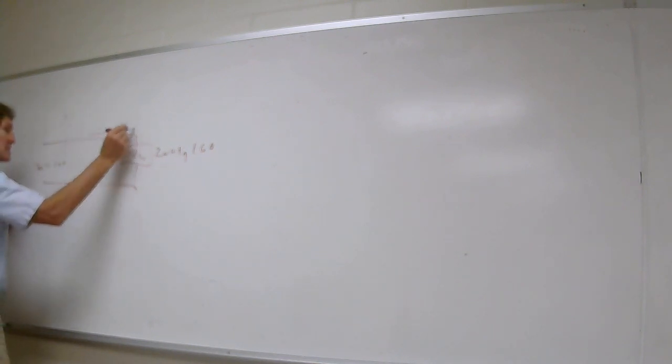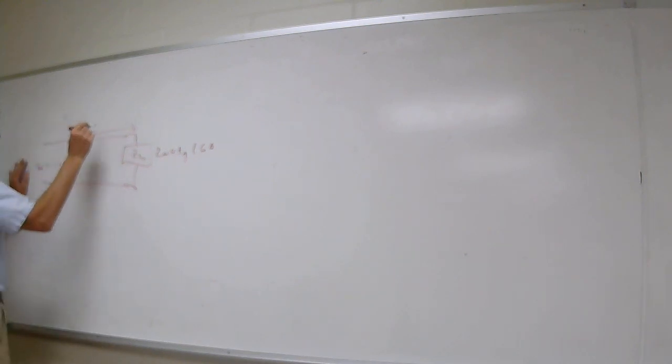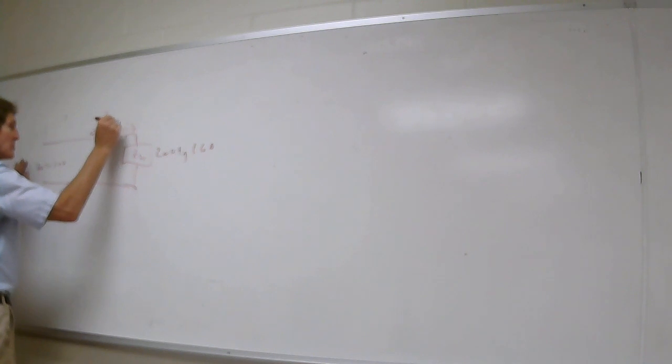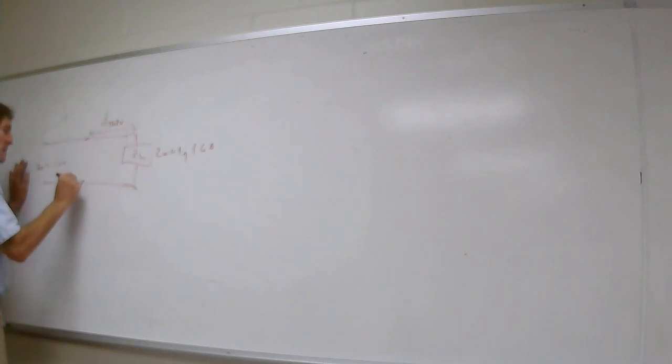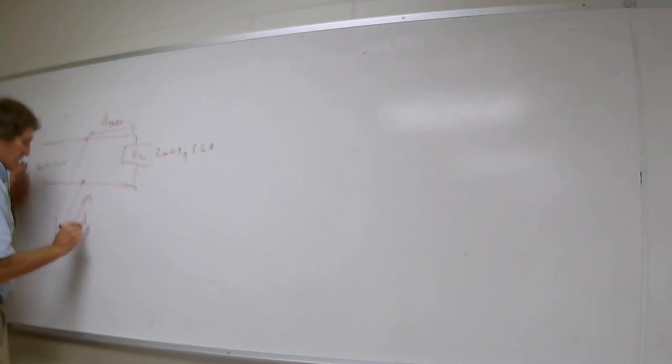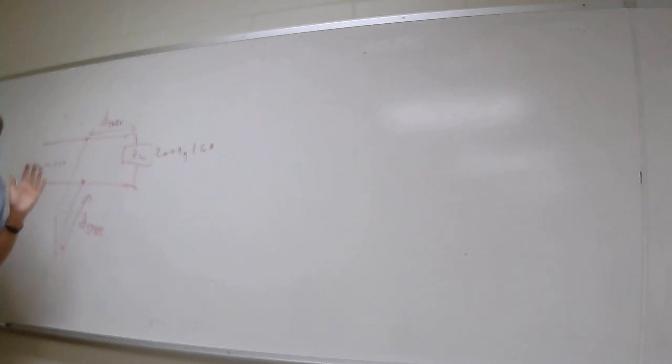We have to figure out this distance, D, and they call it the through line. I'm just going to write THRU, even though it's spelled wrong. And from here, then, is it shunt or is it shorted or open? It's shorted. All right, now we need this distance here, and I think he calls it D stub. I usually call it L stub, but it means the same thing. And it's going to have the same characteristic impedance, okay?